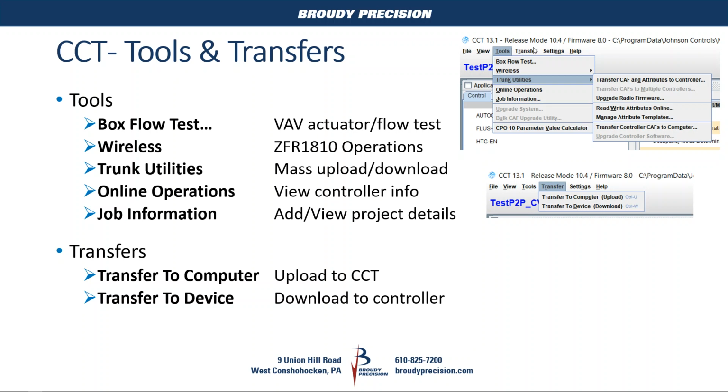And if we move over to the transfer section, transfer is where you would go to do your upload or download of a controller. So transfer to device would be your download, and transfer to computer is your upload. One of the nice things about CCT and the FX series controllers is that if you don't have the application on the controller you're trying to work with, it will allow you to transfer the information back to your computer, and you have the full application to work with, not just a compiled version of it or something like that. You get the full application back in CCT.